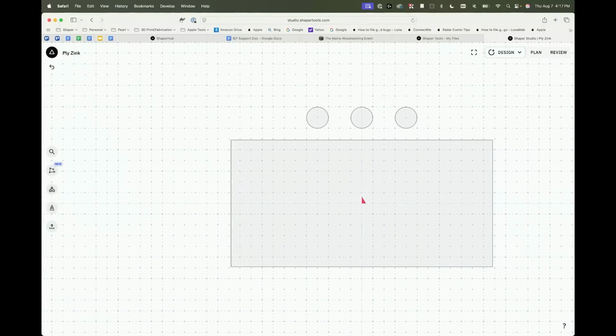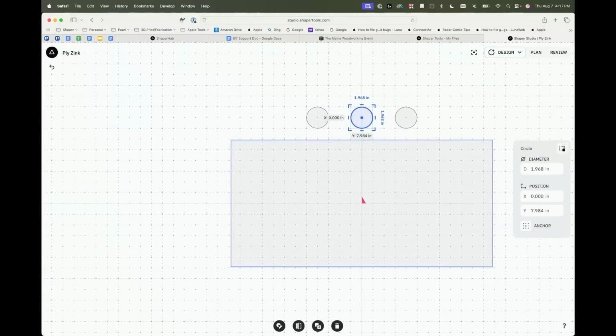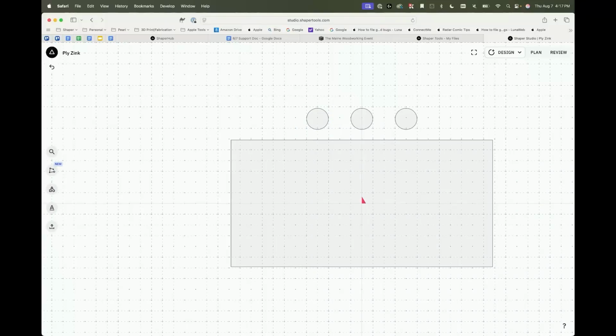And quick check on that. I wanted the center of those circles about 200 millimeters or so from the center of the sink. Okay, cool. So we can just go to the Y and type in 200 millimeters. Boom. I was pretty close. Nice. 200 millimeters. And then same with this one, 200 millimeters. Okay, cool. So now we have our 50 millimeter circles here. They are set up correctly.